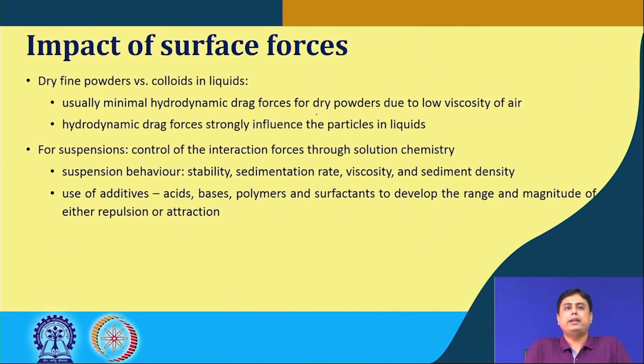Now, the difference between the fine powder and the colloids in liquid is that in air, or in the dry fine powder exposed to air or some other gases, there is very minimal hydrodynamic drag force due to the very low viscosity of the air. But in the case of liquid, hydrodynamic drag force is actually the dominant mechanism, as we have seen in our earlier classes. So it influences the particle in the liquid.